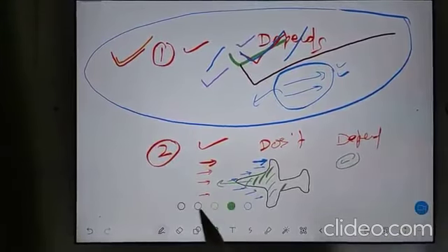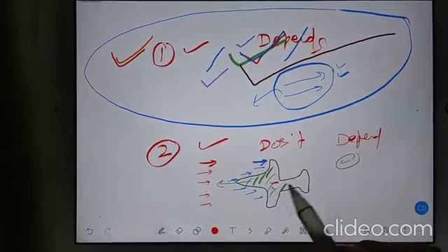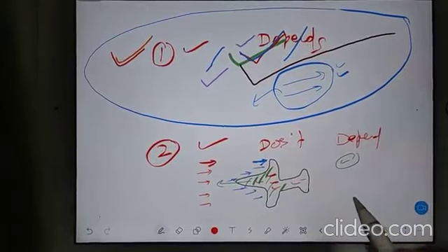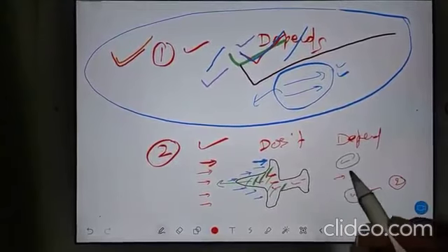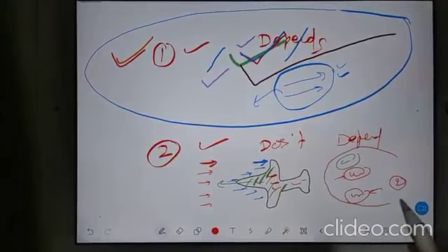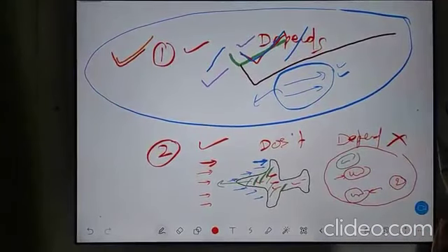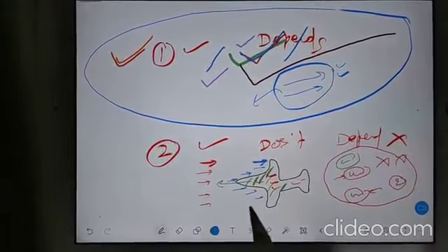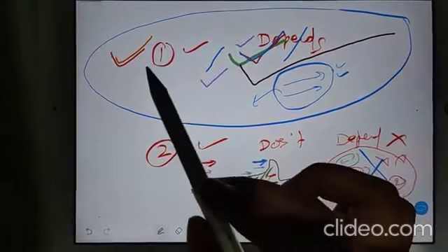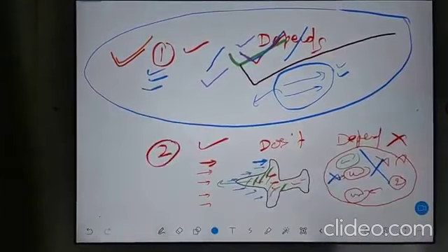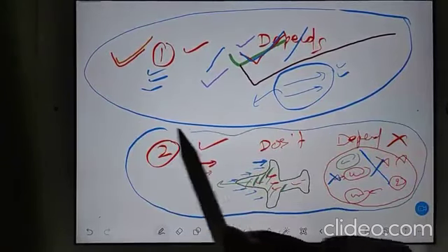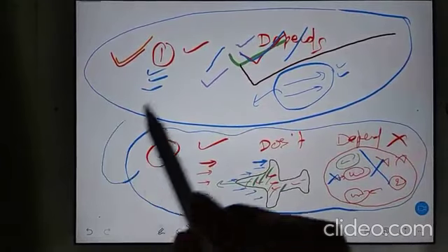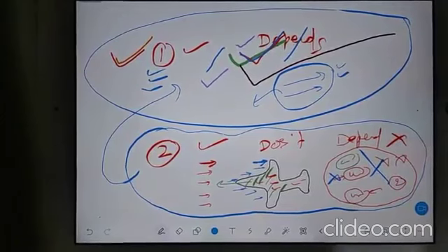Then again, if you have supersonic flow and subsonic flow, then because of that wave drag will come. Okay, transonic drag will come. Okay, you have lift induced drag. So these drags are coming. In this entire drag, where is the weight coming? Weight is not coming. Right? So how can we say drag depends on weight? So this is my doubtful interaction, so that you can think about this in a confused way. Then I will clear this point.